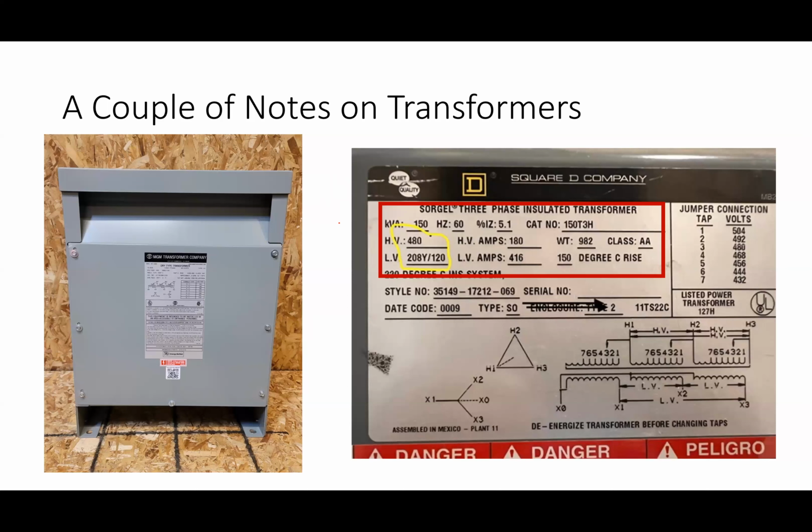What does the fact that there are iron sheets do inside this thing? It helps with the power loss. If I have flux going through a magnetic core, what do we say about steel and iron? They're conductive, so the flux going through that core induces currents in the core itself.